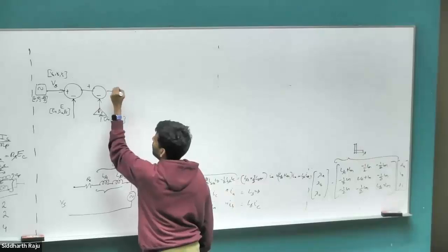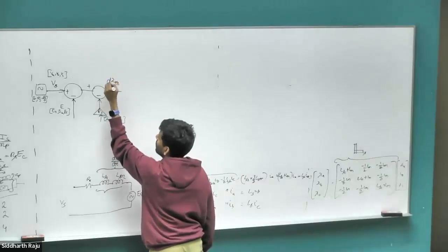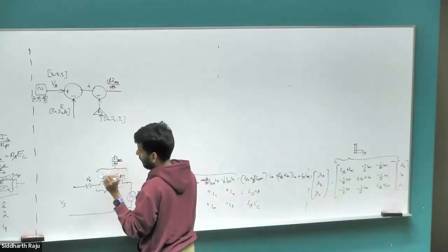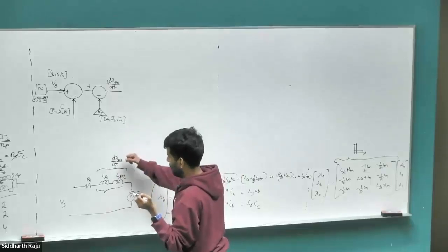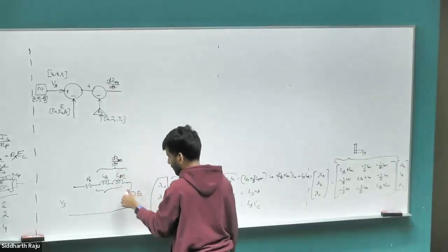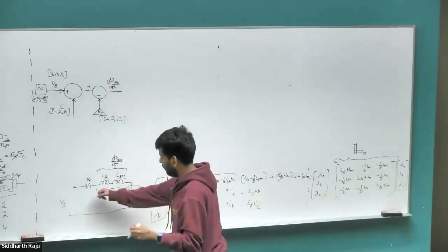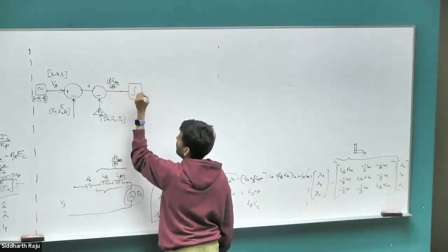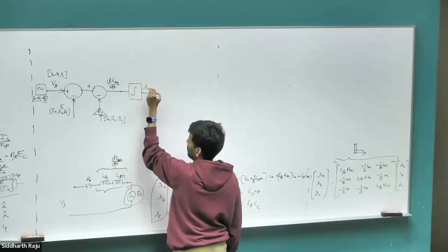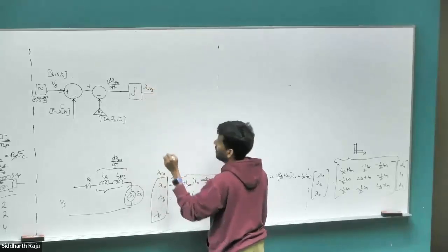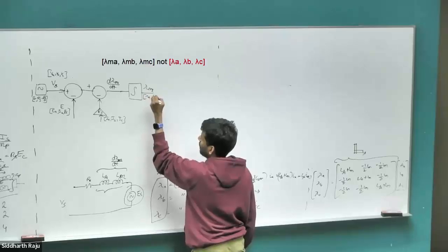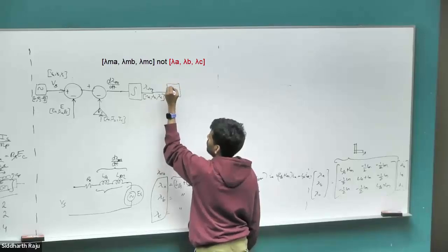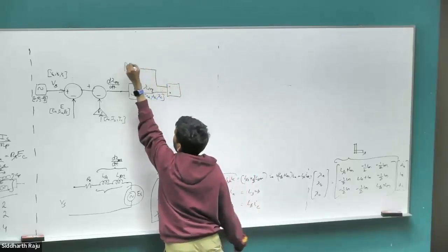So this is going to be d lambda ms divided by dt. This is purely due to the stator currents, the BMS space vector, the BMS magnetic field, not due to BR, because BR is captured by the CMF. Right? We are worried about this CMF. Okay, so we have d lambda by dt. You integrate this, you end up with lambda ms, and that's exactly what this is: lambda ms, which is lambda A, lambda B, lambda C, and then you divide this by the matrix that I have written there.